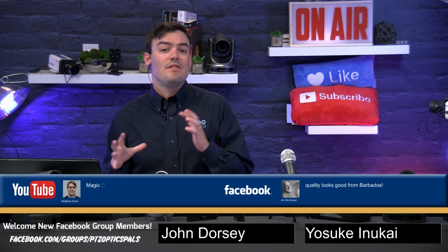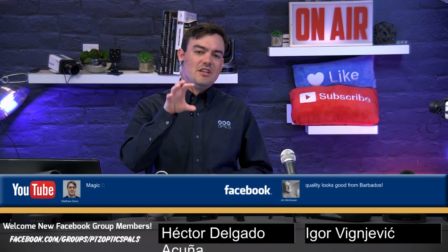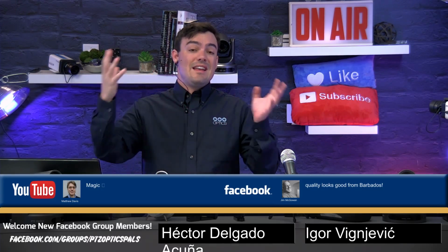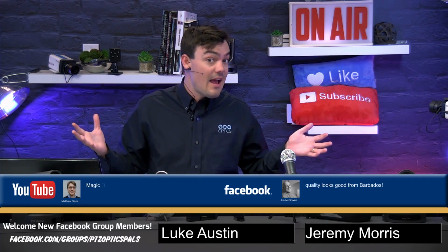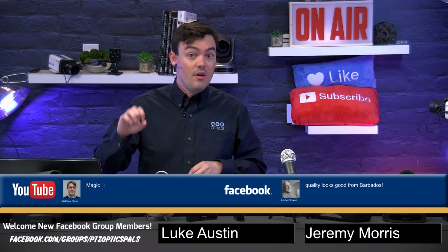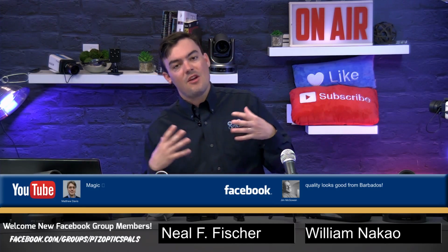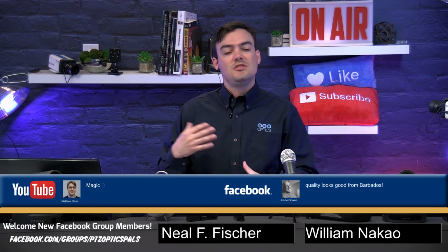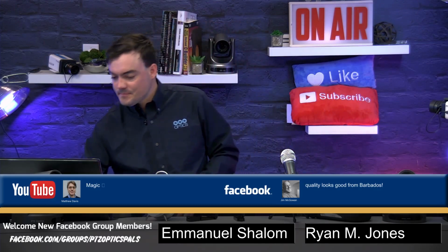Currently, I believe that vMix and the TriCaster are the only ones that support the low definition thumbnails with the high definition switching back and forth. So that way, if you've got 10 NDI cameras, only one is in preview and one is in output. Those other 8 are very low bandwidth on your network, and then we're just using those high definition feeds when we need them. So that's really cool.